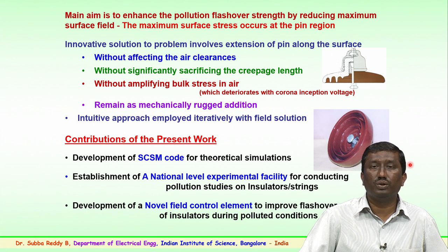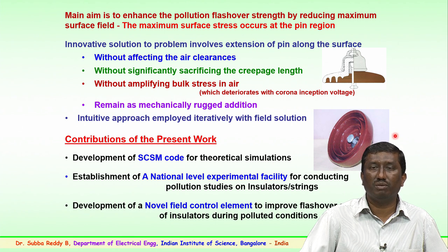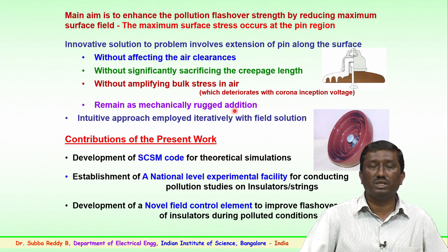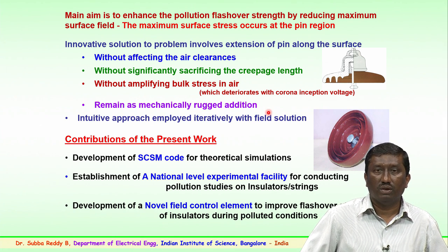So, the innovative solution to solve this problem mechanically could be the extension of the dimension of the pin, without affecting the clearances, without significantly sacrificing the creepage distance. That is, the distance between the metal and the cap is known as the creepage distance, without amplifying the bulk stress in air. So, several of these things have to be taken care of, and also mechanically the insulator has to have a rugged